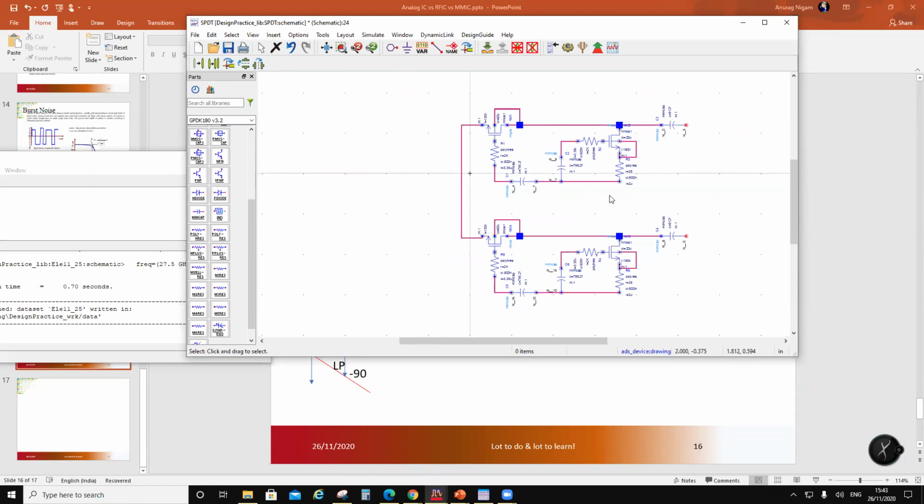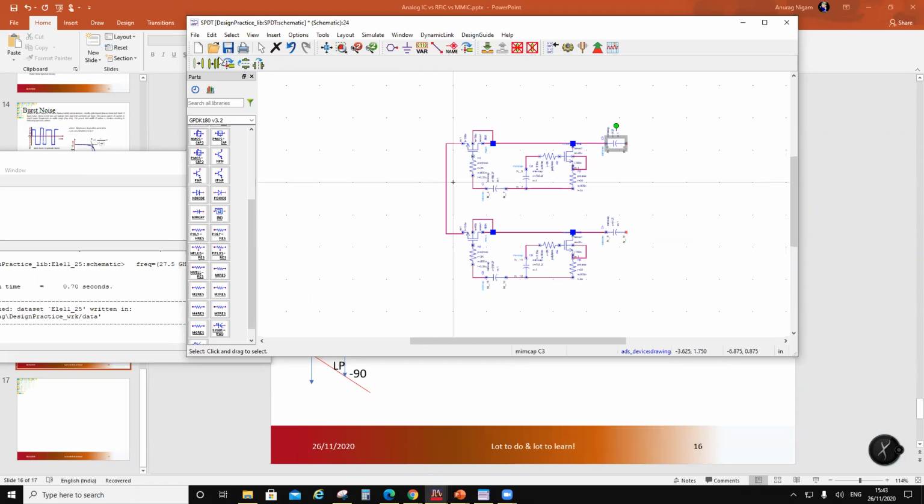So how it works is, I'm going to have a coupling cap over here also. I have port 1 here, port 2 here, and then there are control signals. Let's say this control signal is S. I'm going to turn them on in tandem. So this is S, and this is S, and this one is SB, S bar, and this one is S bar.